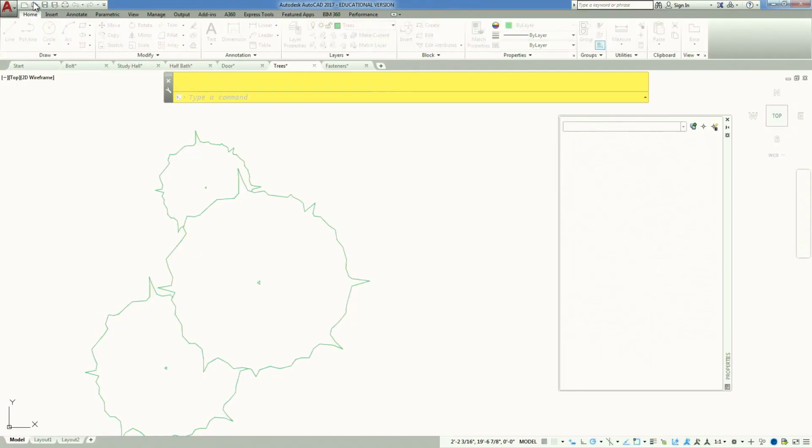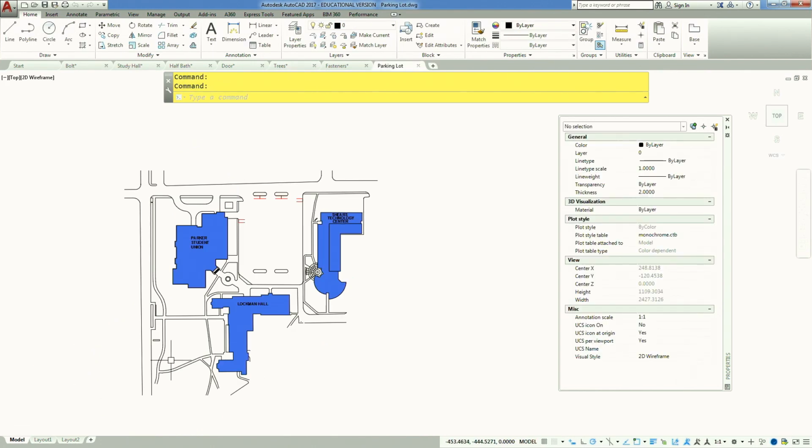Okay, so the next thing that I want to do is work on an array, and then I'll also add an increment to my array. So an array works very similar because it is just a linear value that I'm going to drive. And in my example, I'm only going to drive it one way, but just like a rectangular array, you could do horizontal and vertical. So in my case, I've got these little parking stalls that are 9 foot wide.